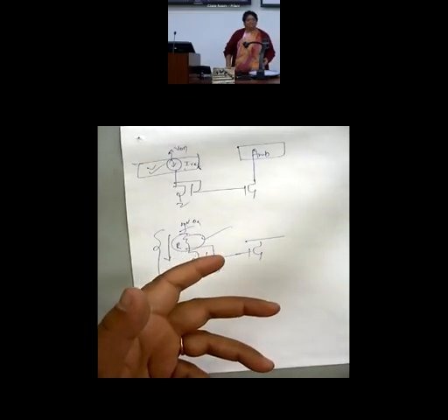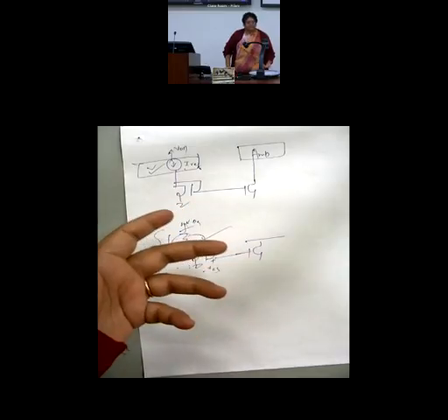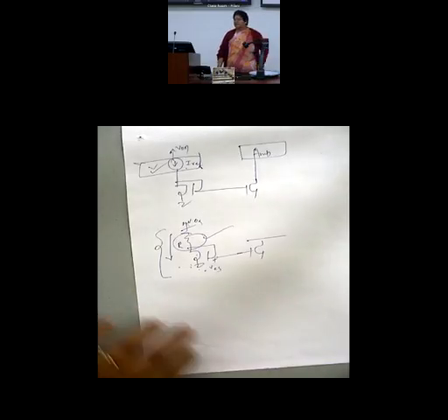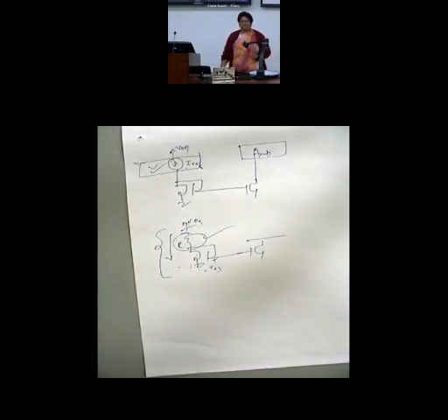Why representing it with a symbol? That is a current source. I could have also used a voltage source. So I can generate either IREF or I can generate VREF. Doesn't matter. Once you generate IREF, you can convert it to a voltage. Once you generate VREF, you can convert it to I. But you can generate both IREF as well as VREF. There are ways in which we can do that. So either generate a reference voltage or generate a reference current. Clear?